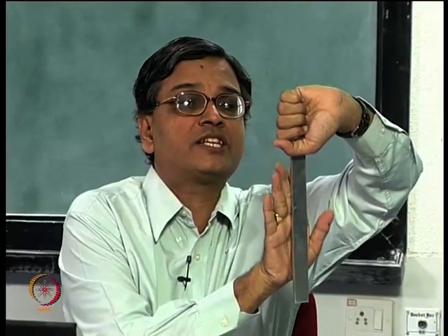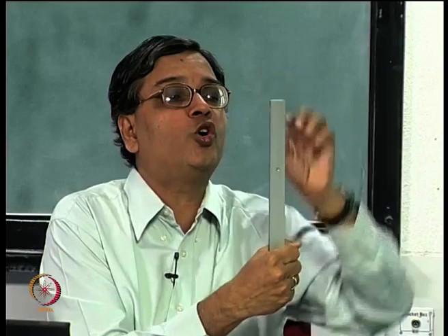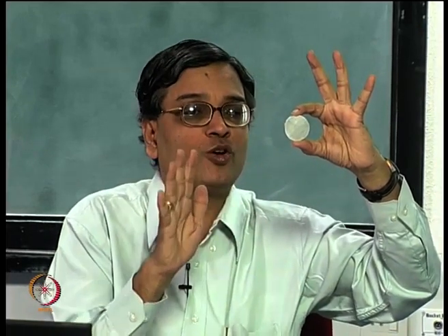On the other hand, other geometries, like suppose I have a circular disc under diametral compression, this you get as a closed form solution from theory of elasticity. And compare, I have an axial member, I pull it, I can do it by strength of materials, but for the same axial member, suppose I have a hole, I cannot solve it by strength of materials, I have to depend on theory of elasticity. Even in theory of elasticity, the hole should be as small as possible. And even if you change the geometry, I do not have a hole here, but the geometry is changed, because of the way I apply the load, plane sections do not remain plane before and after loading. So, when I move from strength of materials to theory of elasticity, I have enlarged my domain of solving problems.